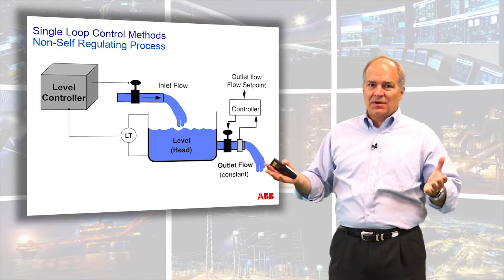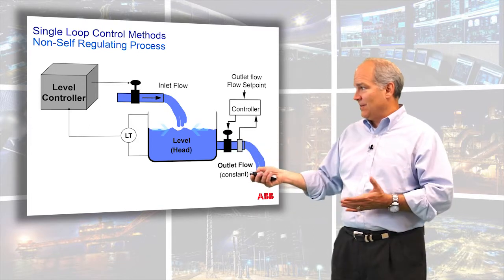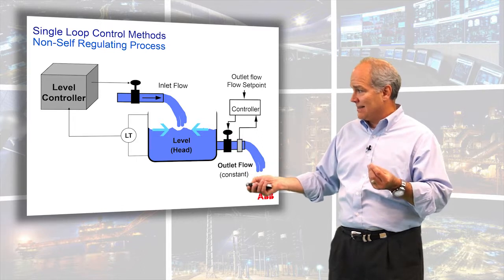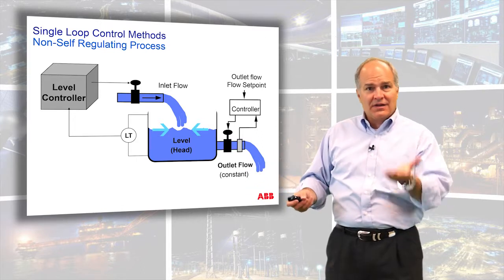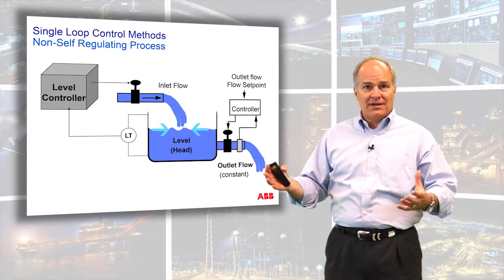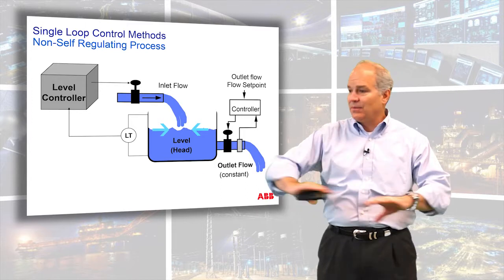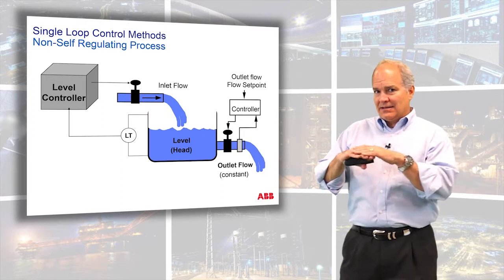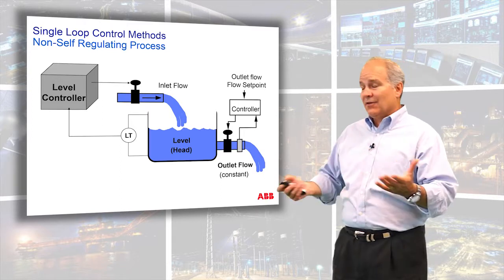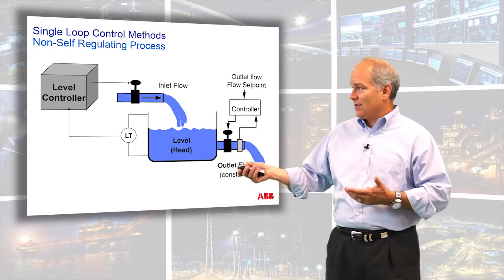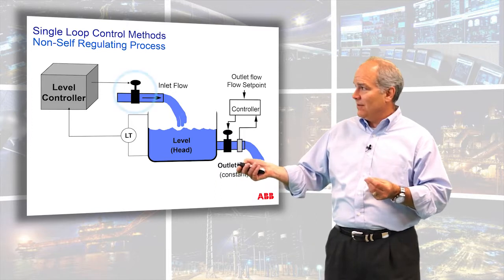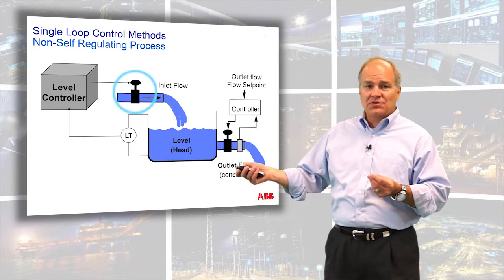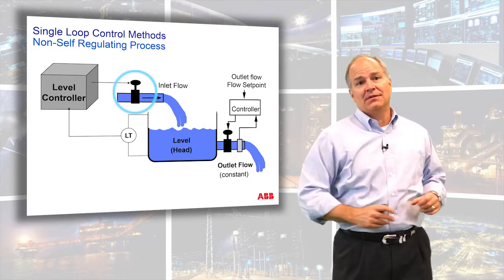We also have to worry about header pressures. A lot of times this level has several outlets. So if it's going up or down, the header pressure is going up and down, which can cause problems that permeate through your facility. So trying to figure out how to maintain this level is kind of important. I've also seen the opposite side: if you try to tune this too aggressively, the quick movements of your actuator can cause problems upstream.